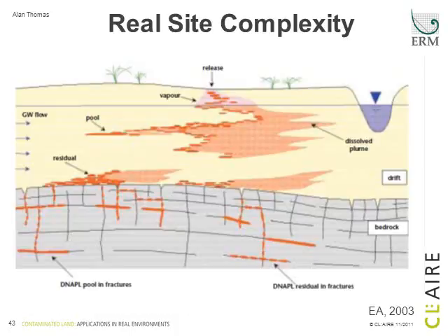At a site level, obviously, there is going to be much more complexity, and this is just an example of a UK site setting where, for example, we may have unconsolidated sediments overlying a fractured bedrock. And in this case, where we've got some DNAPL present, there's a large degree of heterogeneity, structural features controlling the distribution of NAPL, and a whole range of various primary and secondary sources, and a dissolved phase plume. So a complex environment that we've got to somehow assess and deal with.